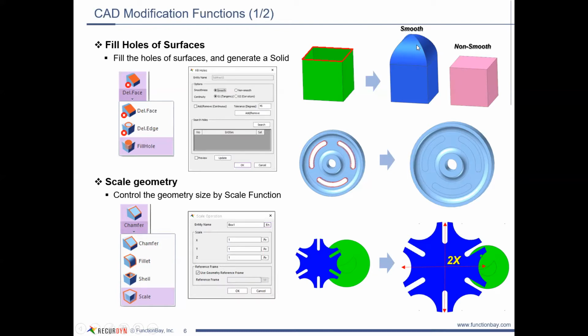It comes up with a pretty interesting shape here, but what it's doing is just trying to make the tangency match of the new surface to the original surfaces. When you pick the non-smooth option, it doesn't try to match the tangent condition there. So it's free to make an abrupt turn and have an angle. In that case, it's just fitting a flat surface over the top. Okay.